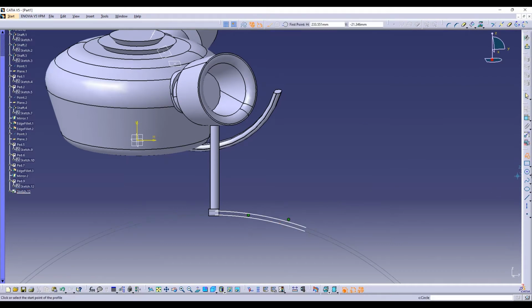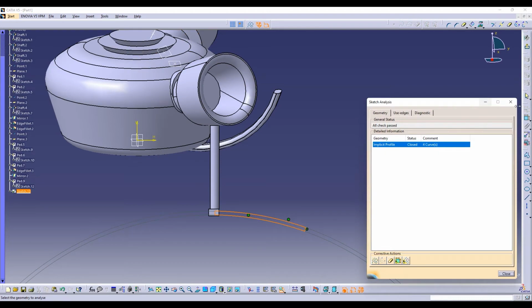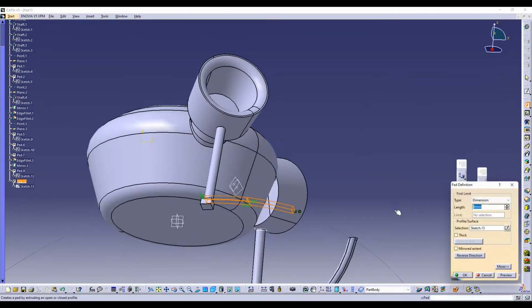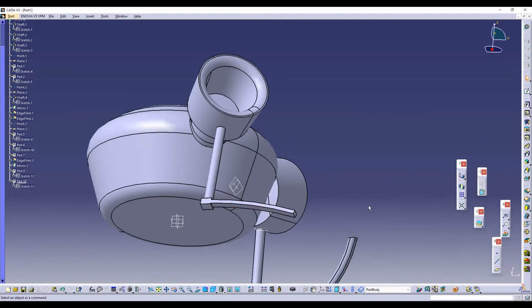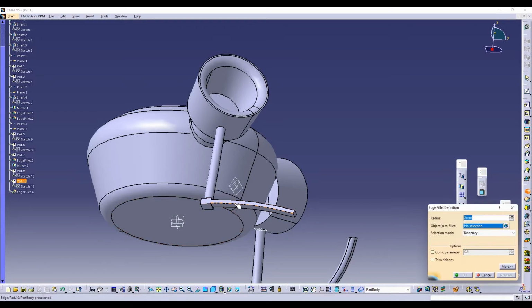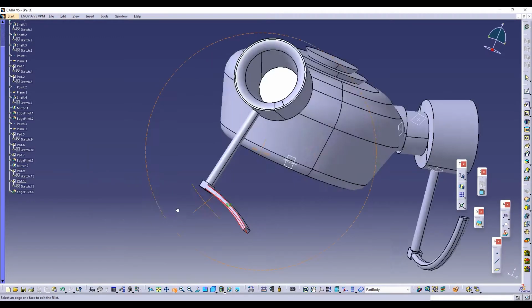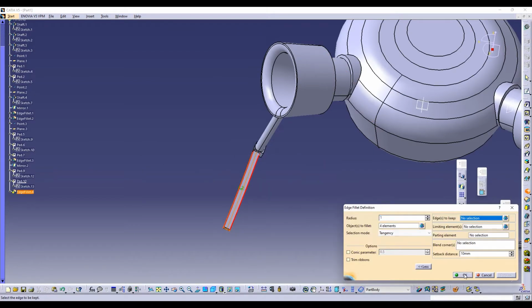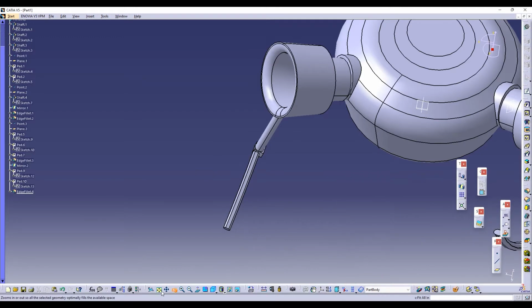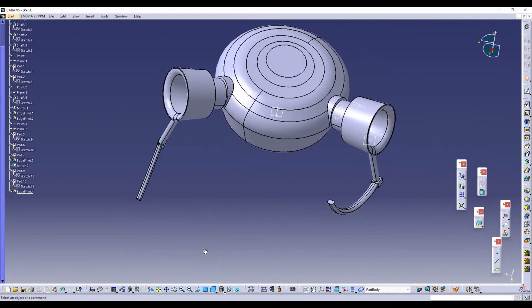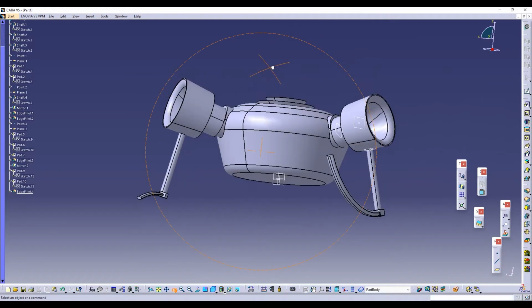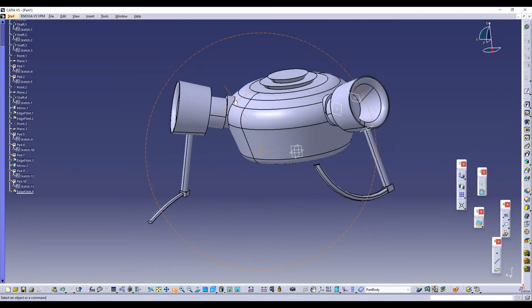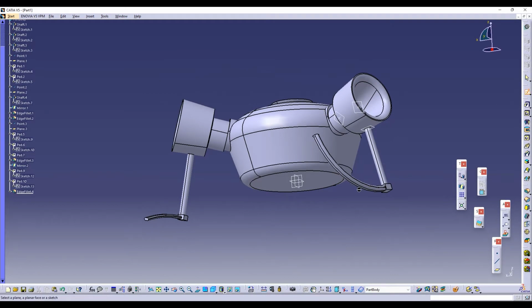On a downside, and we'll offset it. Then we'll join all the lines to make a closed surface. It's done. Then we'll pad it. It's done. We'll make the fillets to make the rectangle a little bit curvy. It's done. Then the robot forearms and the hands are almost completed. We'll go to the next step. Okay, we'll see all the measurements. It's correct.